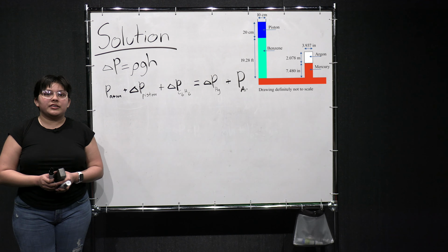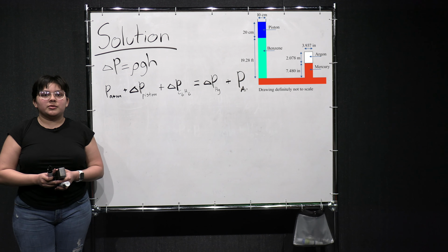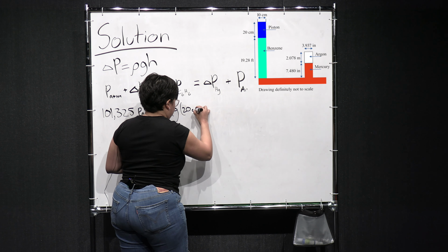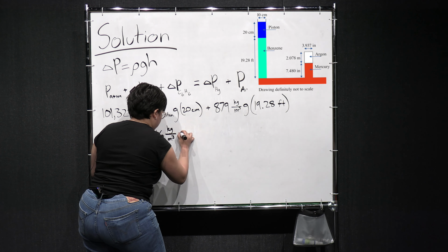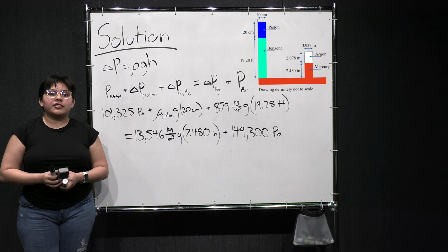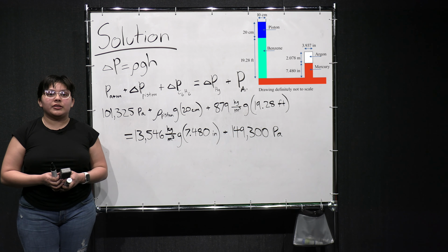Substituting in, the only unknown is the density of the piston, although we do have a number of unit conversions to make. We'll assume you watched the dimensional equations video and have no trouble with the unit conversions. If you convert all of the heights to meters and use g in meters per second squared, then all terms are in Pascal. Solving for the density of the piston gives you 11,500 kilograms per meter cubed, or 11.50 grams per centimeter cubed.